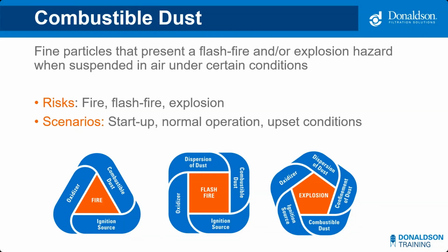That's that middle section. And finally, if you add in the confinement of dust with all these other characteristics, you are at risk for potential explosion. This is a complex issue. We hold separate training sessions dedicated specifically to combustible dust. I'll circle back briefly towards the end of this session, but for now, just know if the dust is combustible, there needs to be a mitigation plan in place to protect workers and property.